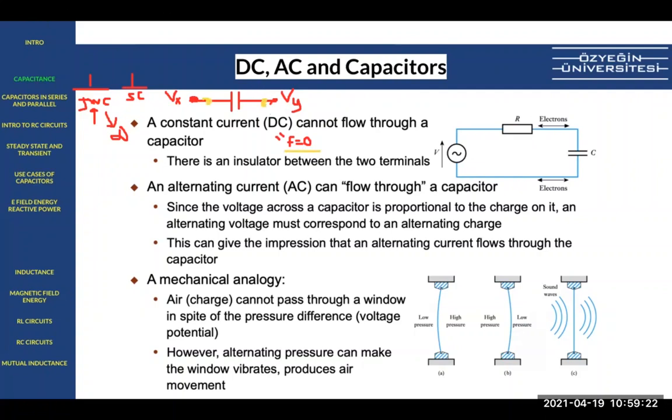So why do we use this? What might be the benefit of that? The benefit of that would be if we have two amplifiers, the DC voltage of this point sometimes cannot really run the circuits. Sometimes they are not compatible. So we just use a large cap between these two amplifiers so that DC-wise, they are disconnected. That's called coupling. So they are not coupled so that we can bias this part with some biasing circuits. We put a voltage here and stuff. And so that we can run this second amplifier with a different voltage.